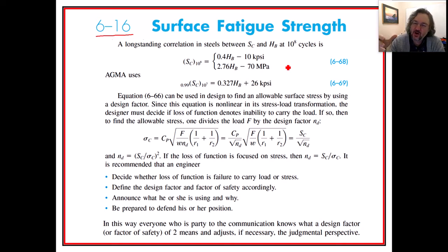If you recall, they take a metal, put it into an apparatus, and make a little dent into it, and it gives you a reading that tells you a range of what the hardness of a material is. Well, that hardness is easily related to the ultimate strength. We can find in Chapter 2 where they have that relationship, and we'll look at that again.